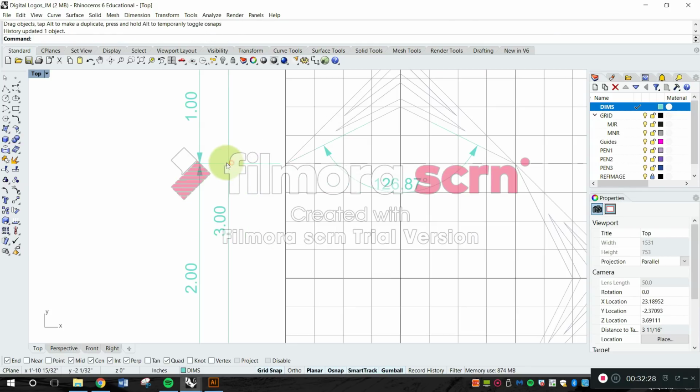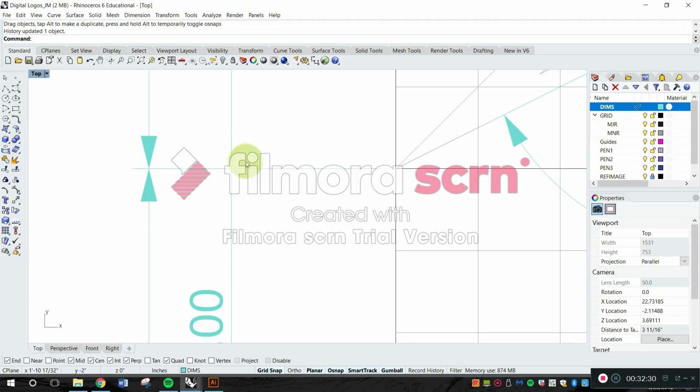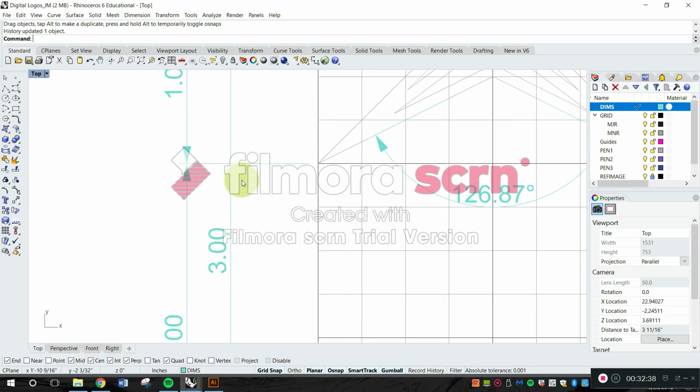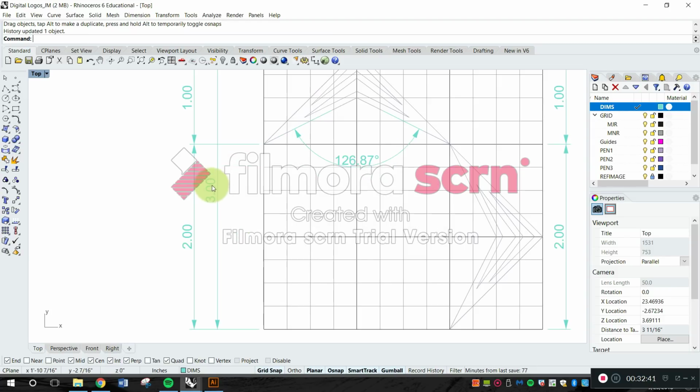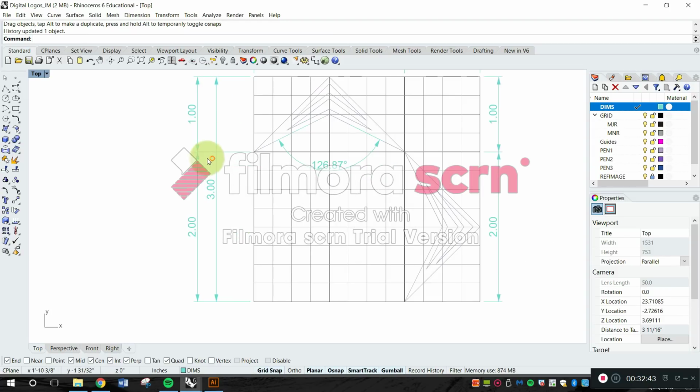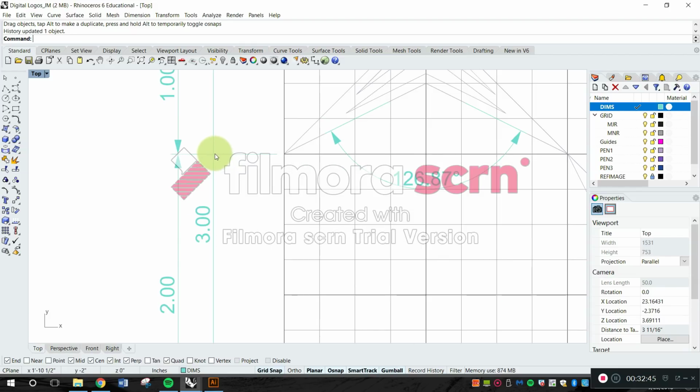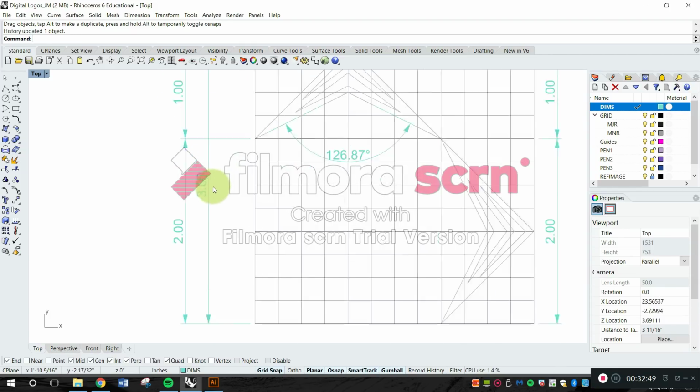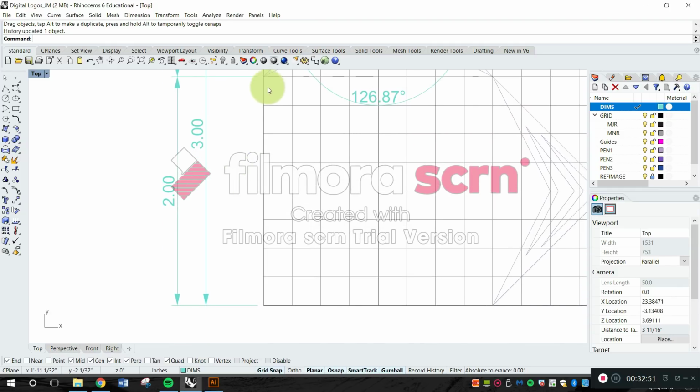Rather than this, guys, coming over. You always, always, always want to avoid this right here. This can really throw things off, especially in a real life scenario, because you're referencing this 3, this overall length, and you're actually crossing it by some other distance right here. So this might be confused, that this segment from there to there is actually 3, and that's not right.